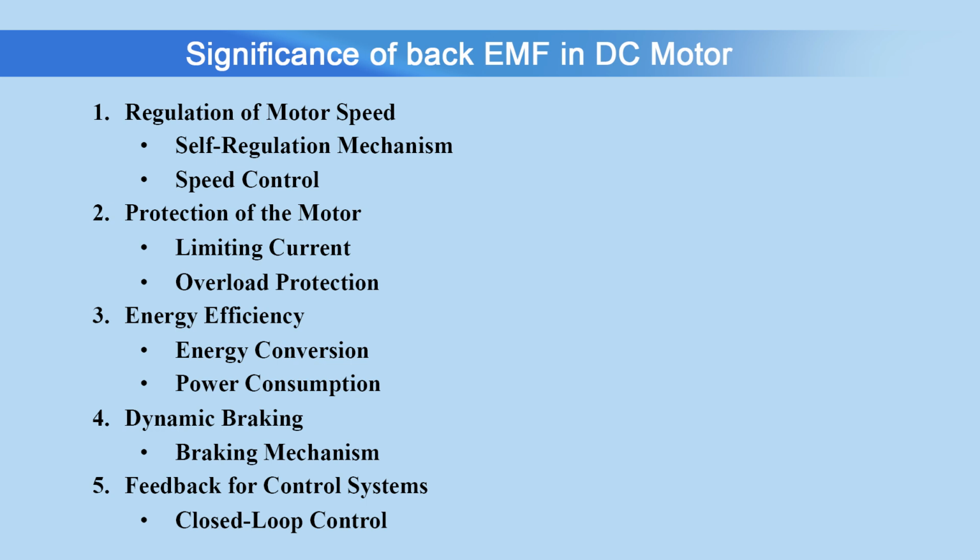The second point is speed control. The motor's speed can be controlled by varying the applied voltage. As the speed changes, the back EMF adjusts accordingly to ensure stable operation.